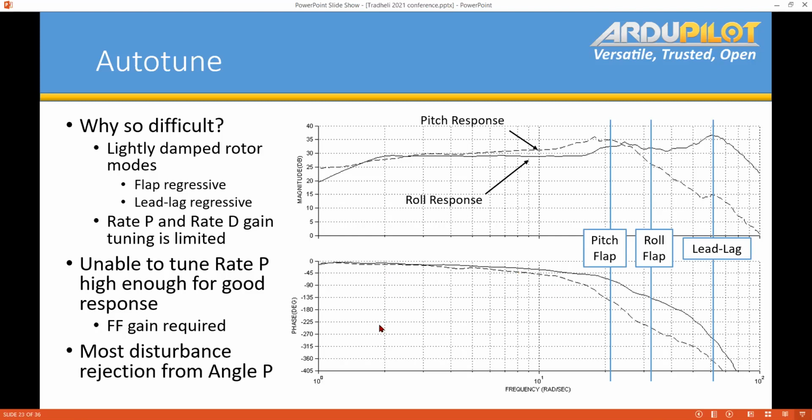And so at these higher frequencies, you see that it's 180 degrees here. That would be when, at this frequency, 10, 20, 25 radians per second, maybe 4 hertz, it's going to be 180 degrees out of phase. Not that you could actually pump the stick that quickly, but your flight controller can, your autopilot. So, kind of the quick frequency domain discussion there.